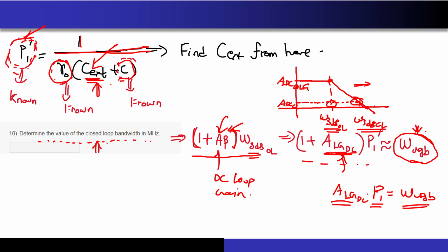Sir, I have a question. Why can't we, like the mistake I did in the assignment, why not calculate the loop gain by multiplying A and beta? A is the DC gain which we got, like 8,000, for the before question. 8,000 into beta, where beta is R2 by R1 plus R2, right? The feedback factor. If you multiply that, we'll get the DC loop gain, no sir. Correct.